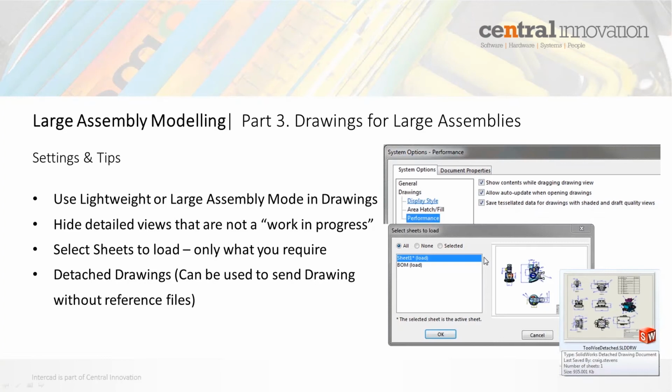That detached drawing can actually have detail and annotations added to it while other people are editing the model, and then the drawing can be synchronized to update once it realizes that the references have been changed. The time to open a detached drawing is reduced because the model file is not loaded. The model data is not stored in memory, and that gives you more memory available to process the drawing data.